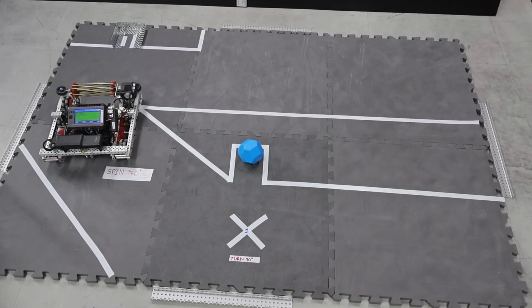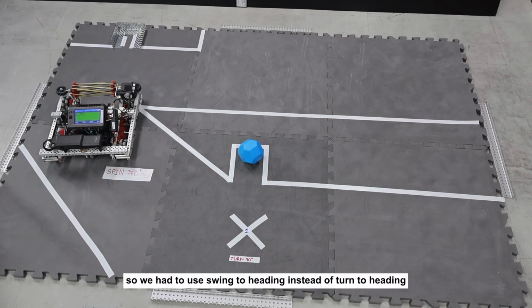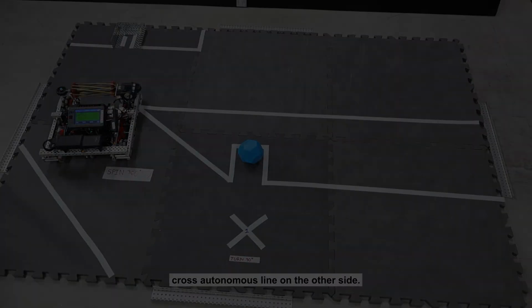So to conclude, our swing to heading command is really useful for areas which you need to turn very sharply. For example, in High Stakes last year, we didn't want to touch the autonomous line when going up to pick the middle rings. So we had to use swing to heading instead of turn to heading, so our wheels wouldn't cross the autonomous line on the other side.